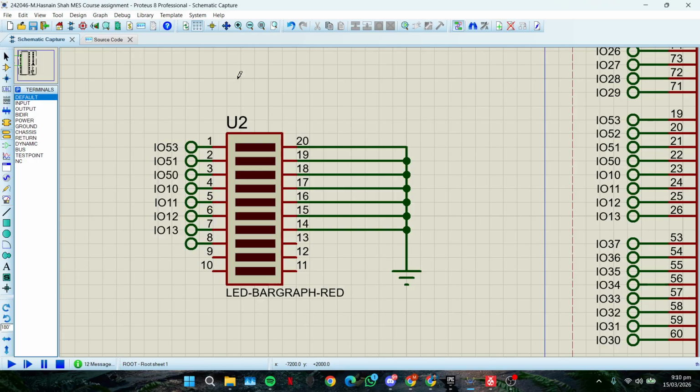Okay, so what will happen when I simulate this? In the chip settings, I have matched the clock frequency to the F_CPU defined by my code, which is 1 megahertz, to ensure the delay timing is accurate. So the result: when I play the button, okay, let's play it. This is the pattern that we should observe. You can see the port pattern instantly flipping. The LEDs that were on go off and vice versa. It will perform this swap 200 times before coming to a stop at the while command.